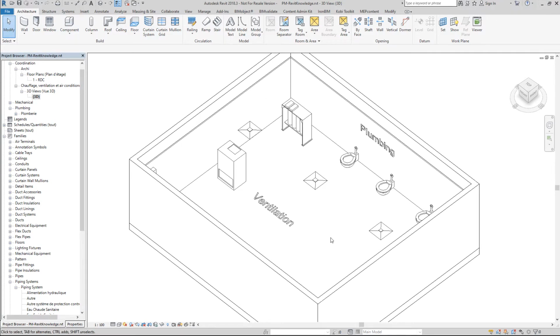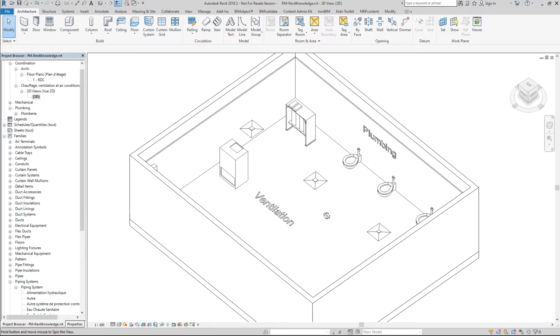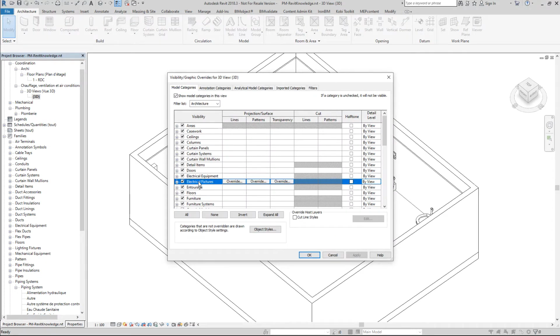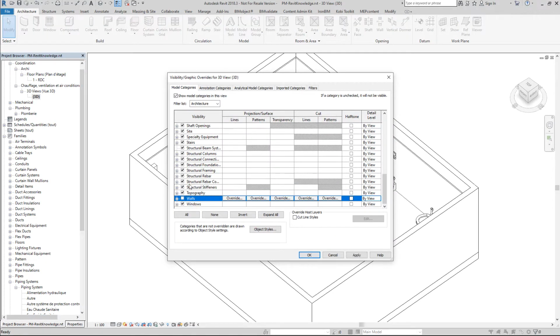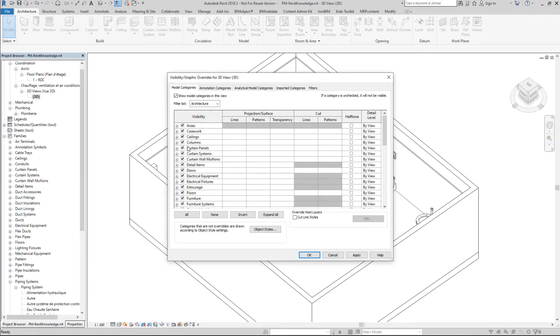As you can see here, you have sources of the system and the terminals, and in Revit you go from the terminal to the sources, so it's important to differentiate both, and we will see that it is also important to have this difference in the connection. I will simply hide the walls and the ceilings that are not really necessary for the presentation here.